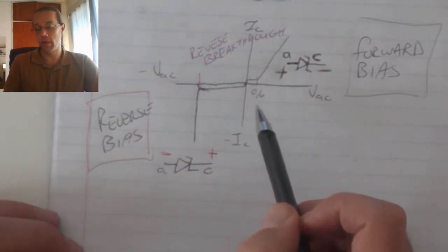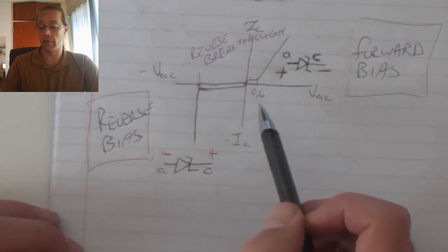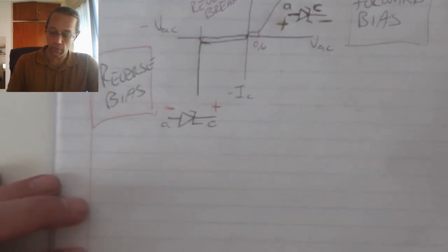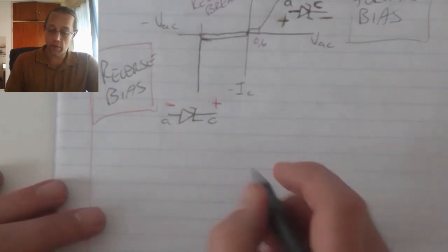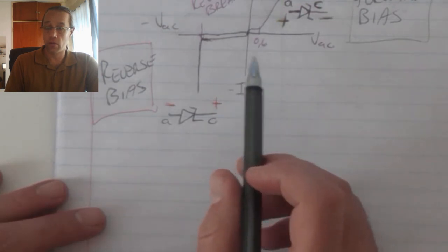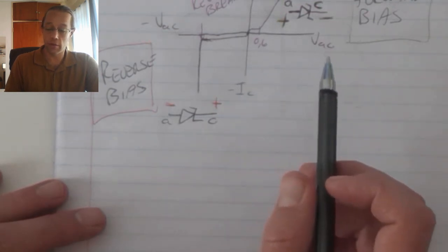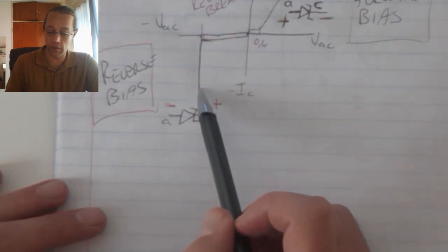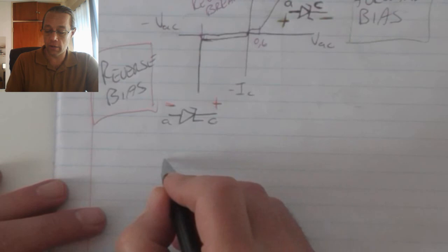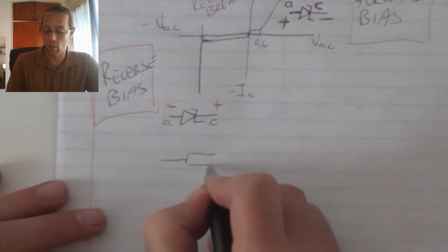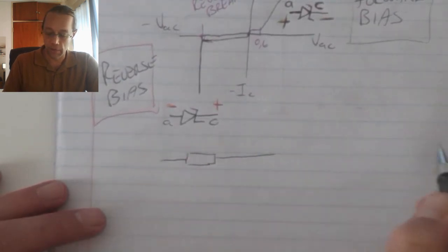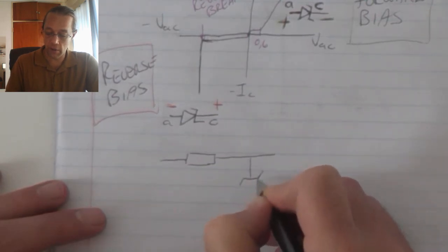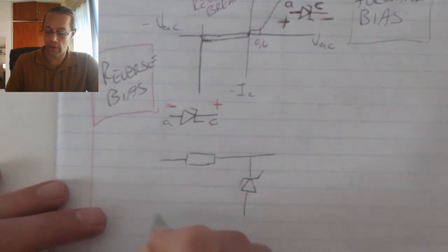The Zener diode is specifically designed to operate in reverse bias so that it can serve as a voltage regulator. Now, in order for us to ensure that Kirchhoff's law isn't broken and to protect the Zener diode from situations where we have excessive current flow through it, the Zener diode is always connected in series with a resistor. That resistor connects in series with my Zener diode,